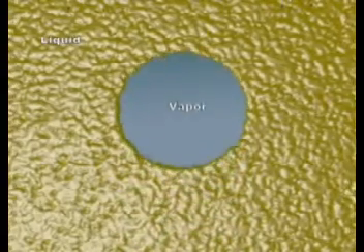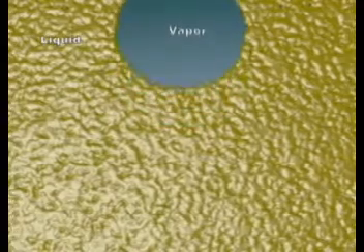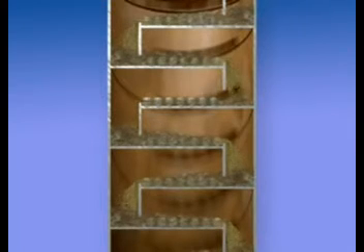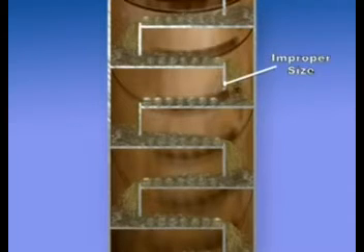When the hot vapor makes its way through the liquid, heat is transferred to the liquid. Some of the vapor will condense as a result and is added as liquid to the tray. At the same time, because of the heat transfer, the liquid will boil and generate more vapors. The continuous contact between vapor and liquid on each tray brings out the separation between components with lower and higher boiling points.